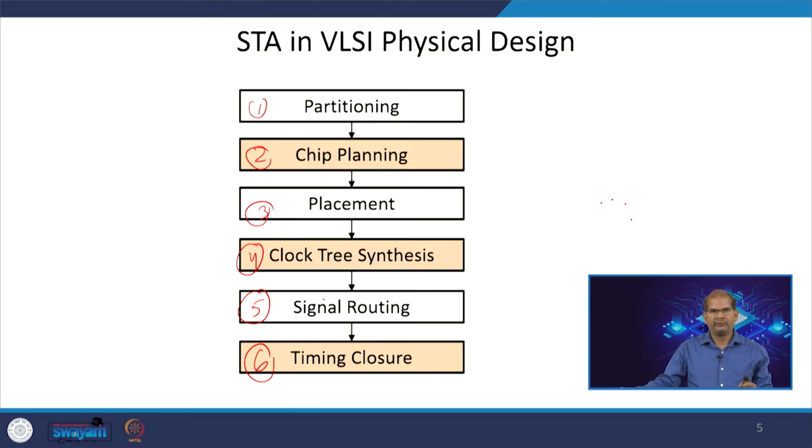And whenever we go to clock tree synthesis, because in the initial logic synthesis phase we assume that our clock tree is ideal, but during clock tree synthesis there will be a lot of buffer insertion and a lot of routing resources added in the clock tree. Then the clock skew and clock jitter need to be considered. So, that will add to our timing. After the clock tree synthesis, we have to check the timing, and if it is violated, we go back and fix the timing.